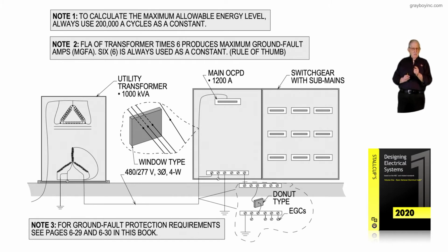He said, now if it still fails to function reliably, take 15% of 2,000. And if that still gives you a problem, nuisance tripping, go up to 20% of 2,000. And if you still have a problem, we need to come out as the manufacturer and take a look at it.